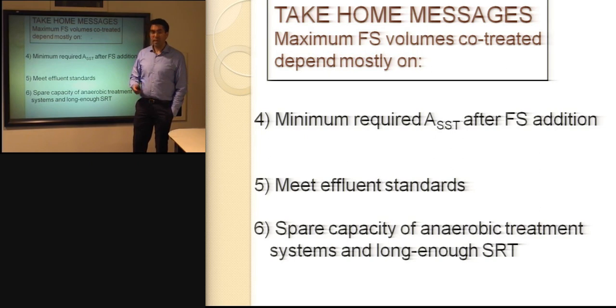So, based on all these concepts, what we can say is that if the plant is not built ex professo or upfront for the treatment of fecal sludge, either under aerobic or anaerobic means, the risk of having a plant that goes out of stability or becomes overloaded is very high.